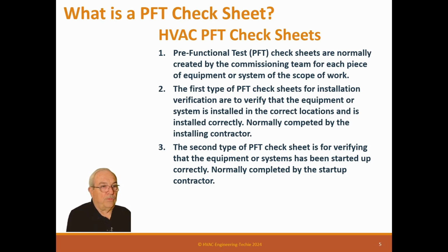If we get the voltages back and there's 15 to 20% difference in the phases, something's wrong. We want to know that exact data. We want to know the fan suction pressure, discharge pressure, all that stuff that's happening during startup we want to see. And if you don't have it in your check sheets, you're never going to get it.